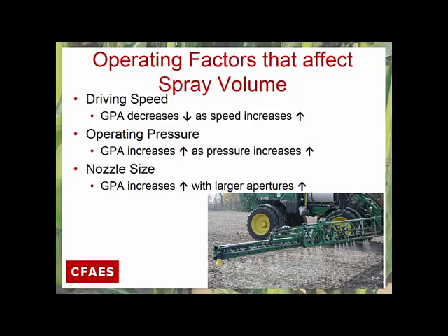Of course, if you have a rate controller on your sprayer, these are designed to hold your gallons per acre or your spray volume steady. So as you, for example, increase your driving speed, it's going to increase your spray pressure, or in this way keep your gallons per acre constant.